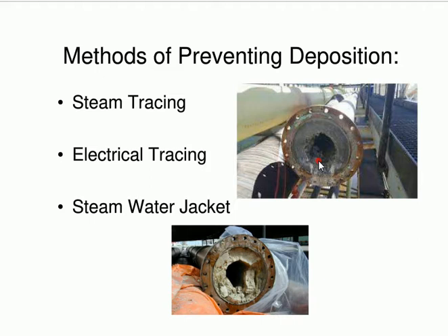And so the idea with any of these methods, with steam tracing, electrical tracing, and steam water jackets, is to just warm up the pipe to stop deposition from taking place. So that's all. You just warm up the pipe. That's really the whole technology behind it.